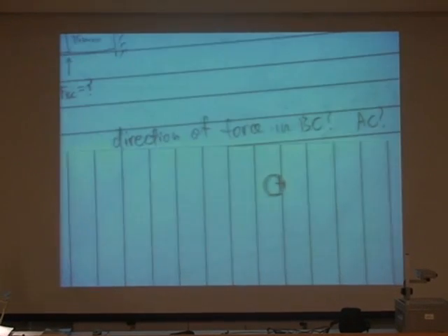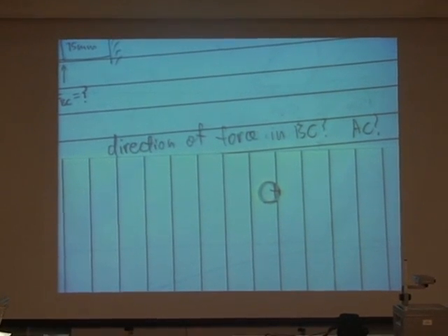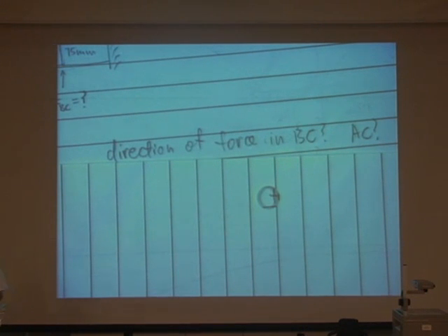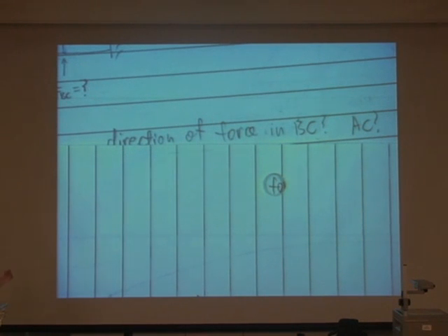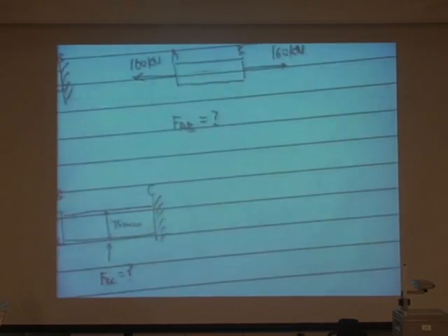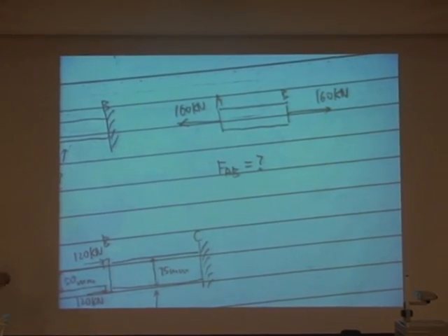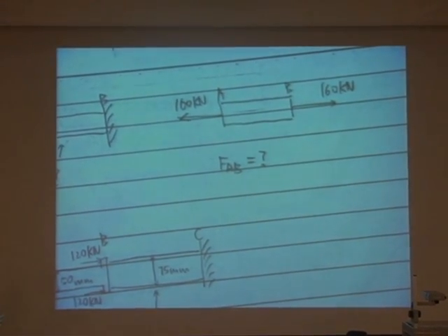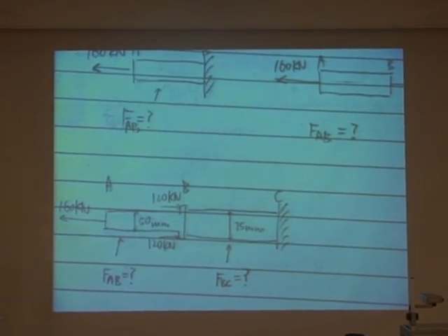What are the other forces that it's experiencing for the second part? Other possible forces: from the wall reaction. The wall gives it a force, correct? So in order to maintain static equilibrium, this force comes from the first part, and this force comes from the wall. They will just cancel out each other so that they can maintain static equilibrium. So in the end, the force from the wall we immediately know is 80 in the leftwards direction. Okay. So this is the way we do force analysis.